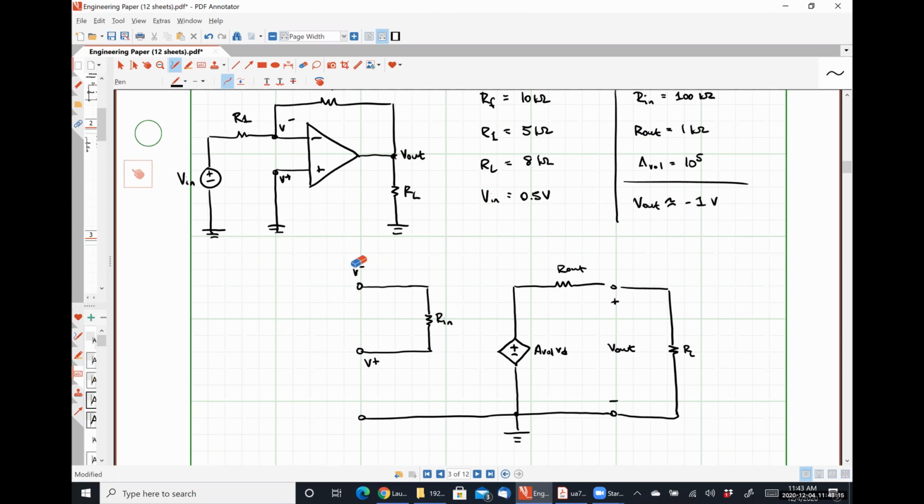We'll go ahead and do my feedback resistor. So this was V minus. So I have a resistor placed between my inverting input and my output terminal. So this is my feedback resistor, RF. I have my resistor R1 placed between my inverting input terminal and the node point connected to the positive polarity terminal of my voltage source.